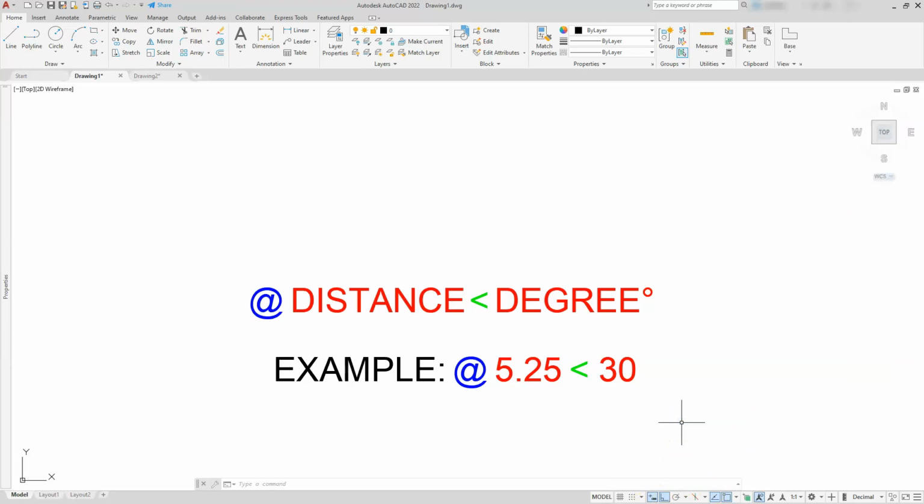Another thing that we're going to take a look at when we're doing these angles is two other special ways of doing it. You can either use ortho mode, or F8, or you can use polar tracking, which is function key F10. This one is controlled by F12. I know it doesn't say that in the little tooltip that pops up beside it. You can either click this icon or F12, or function key 12. It's going to be the exact same thing.